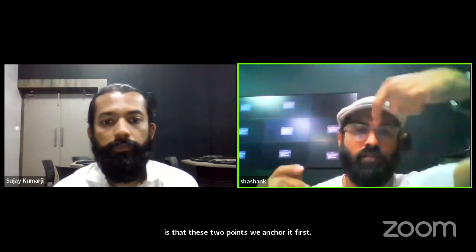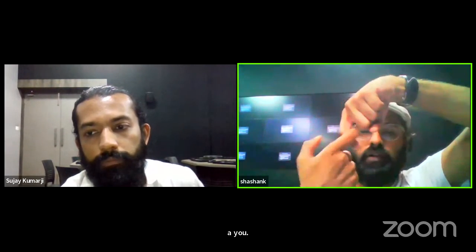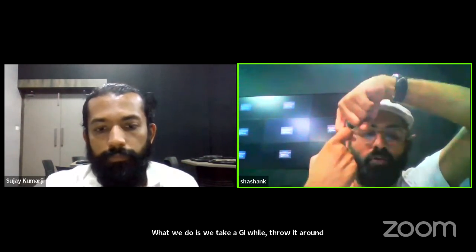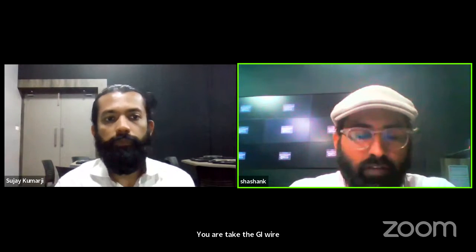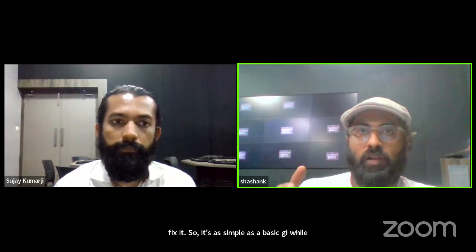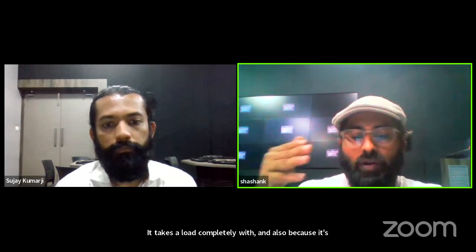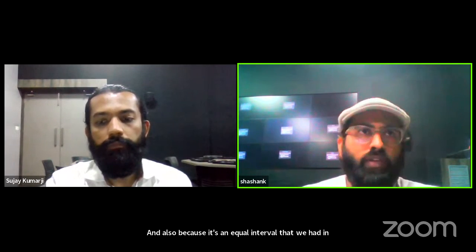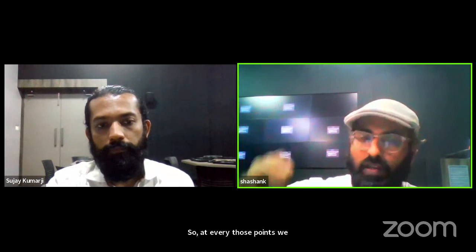So you already have an anchor, like a U anchor like this. What we do is we take a GI wire and throw it around, because there are already perforations in the pieces. You take the GI wire and fix it. So it's as simple as a basic GI wire. It takes the load completely, and also because we had these anchor points at equal intervals, we calculated that every 2 feet, 3 feet, we have an anchor point. At those points, we had this GI wire taking up that load.